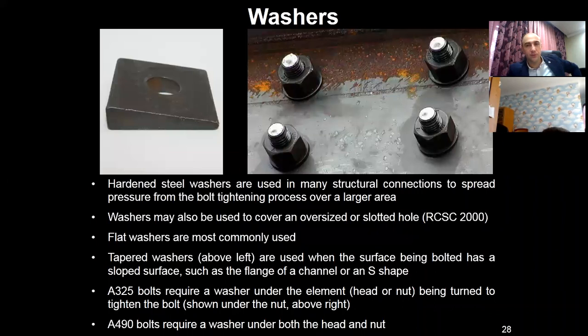Washers. Bolting actually connects several pieces, and one of the important ones is not only the head but also the washers. Hardened steel washers are used in many structural connections with the main aim of spreading the pressure from the bolt tightening process over a large area.